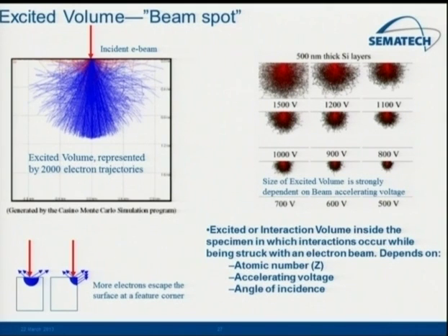You're putting more of the energy near the surface. The secondary electrons that escape are actually only coming from the surface sites. So the reality is if you increase the electron beam energy, you're putting most of your energy at a place where you're never going to see the secondary electrons either. So a lot of the optimization for semiconductor-specific CD-SEMs has been to build tools in this sort of voltage range with low penetration while also keeping the beam very stable. Higher energy is actually easier to focus and control the beam than very low energies.